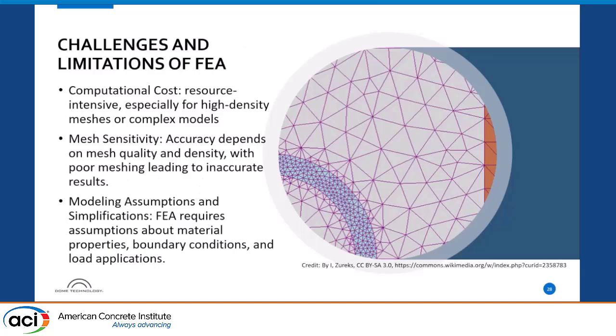Some of the challenges that we run into is that it's computationally costly to run these models. With the availability of computers today, and not just computers, but fairly fast computers, we can address that computational time. You have to know that mesh really well and where you're going to have problems. Looking for a mapped mesh will help check different areas like this that are going to be a problem, and meshing it appropriately.